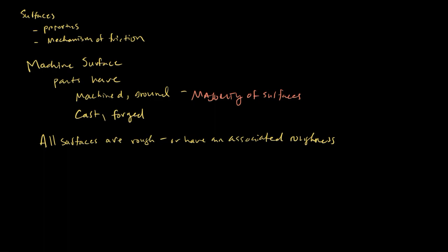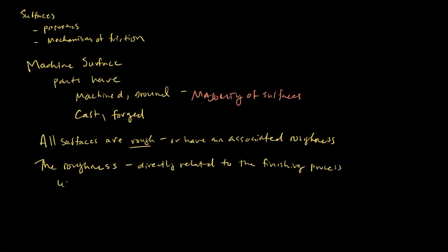Depending on the application, rough is a qualitative word, so a rough surface in one application may be a very smooth surface in another context. The roughness of a surface is directly related to the finishing process used on the surface.